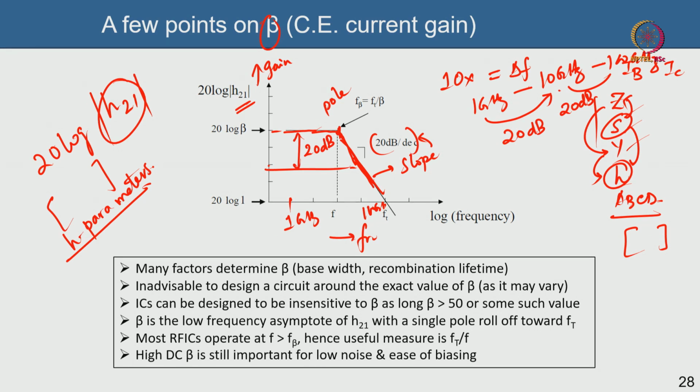The underlying physics or the understanding is that the gain you get, which is essentially output by input, falls off with frequency. Why? Because as you increase the frequency, your carriers have a finite speed. So, as you keep increasing the frequency of the signal, your carriers are not able to catch up with the signal as much. So, as you keep increasing the frequency, the gain that it will offer also falls. The gain at low frequency is very good, but with higher frequency the gain will fall off.